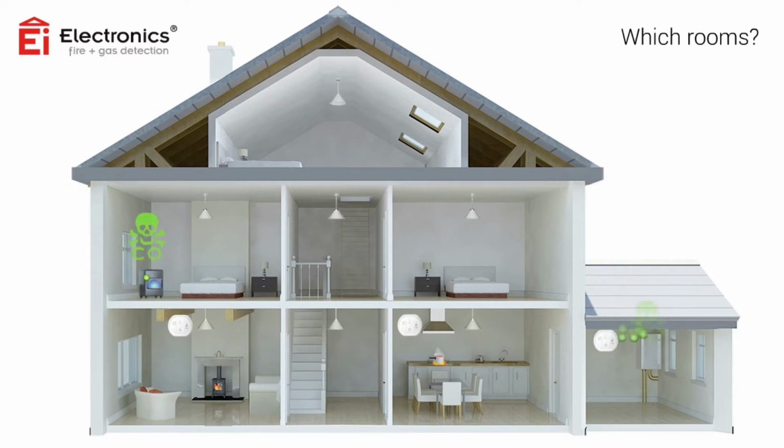If it is not feasible to fit an alarm in every room with an appliance, priority should be given to rooms with flueless or open flue appliances and rooms of high occupancy, for example, living rooms and bedrooms.